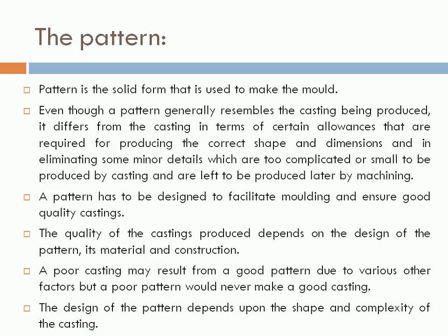A pattern has to be designed to facilitate the molding and ensure good quality of the casting. The quality of the casting produced depends on the design of the pattern, its material and its construction. A poor casting may result from a good pattern due to various other factors, but a poor pattern would never make a good casting. So the importance of the pattern in casting is great,